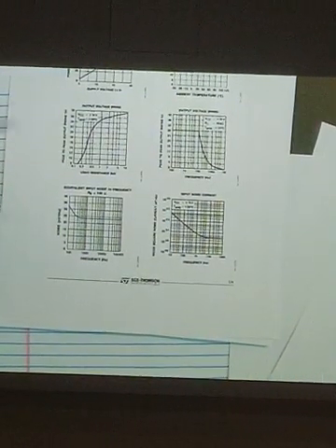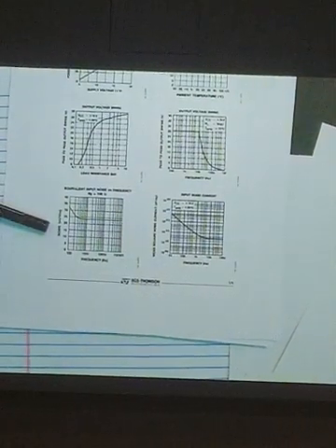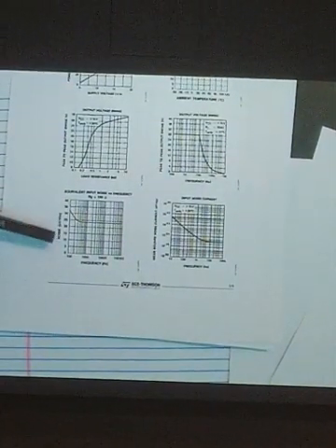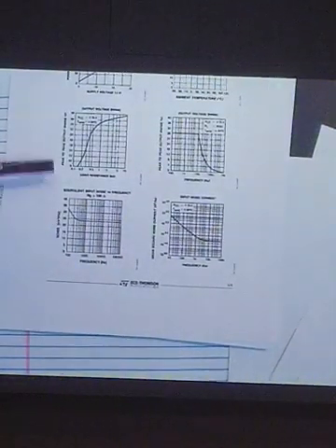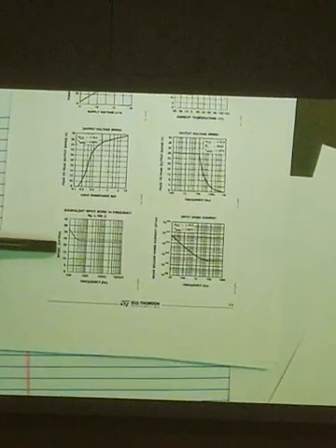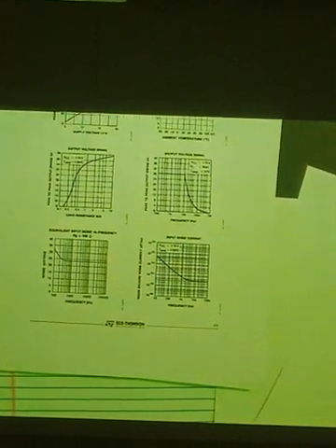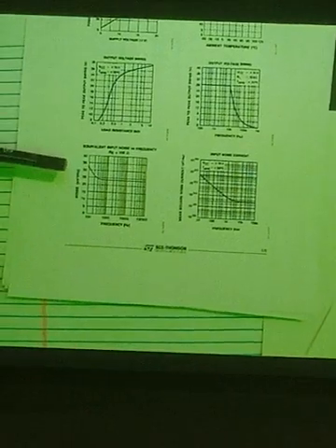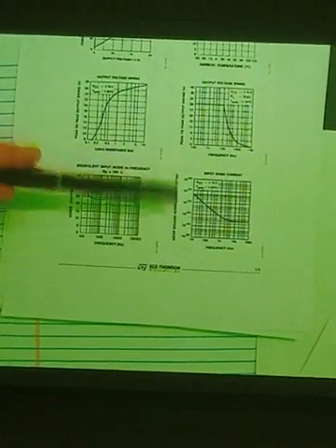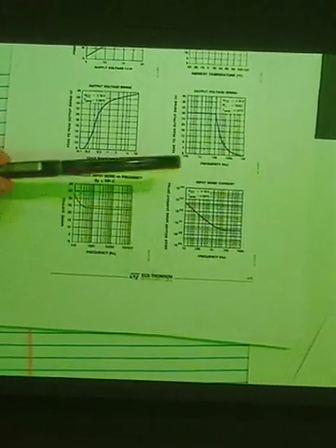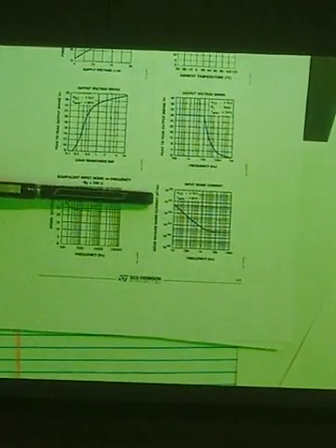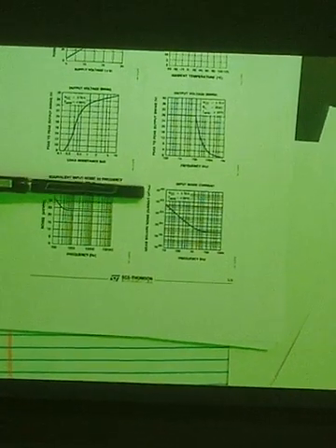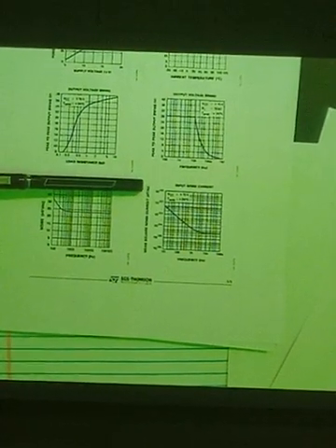In one case, the units on the noise voltage are nanovolts per root hertz, and you can see this is 5, 10, 15, 20, 25 nanovolts per root hertz. On the other side, little oddball units: the input noise current is mean square noise current, so that's amps squared per hertz.